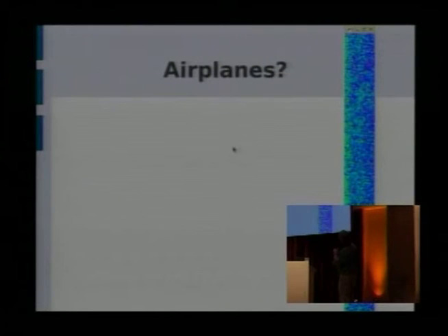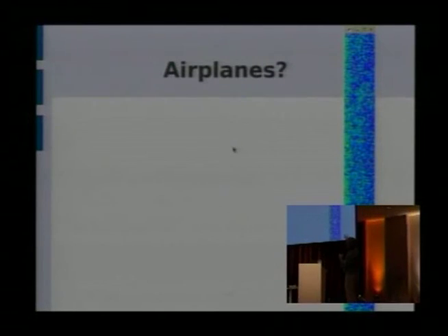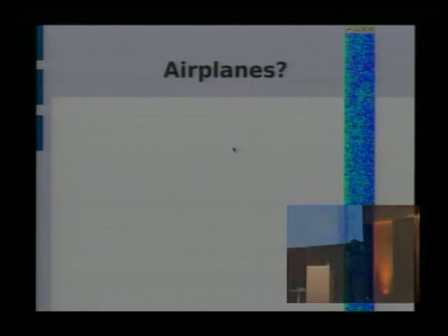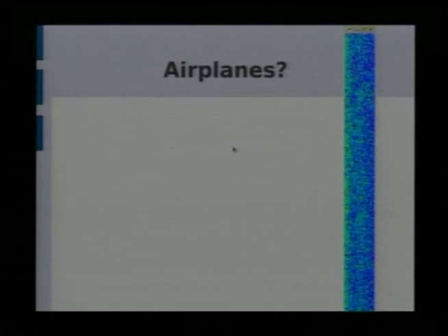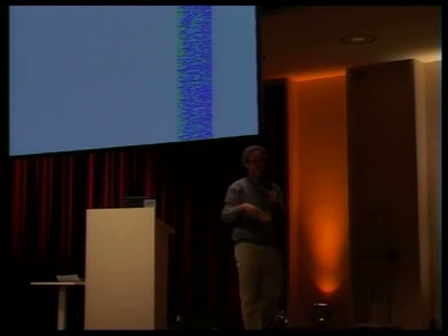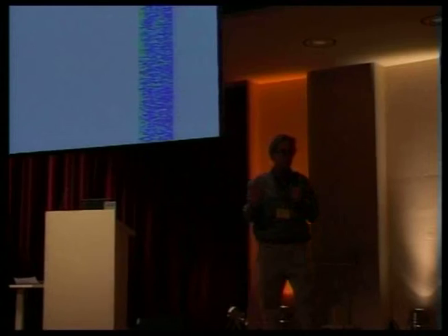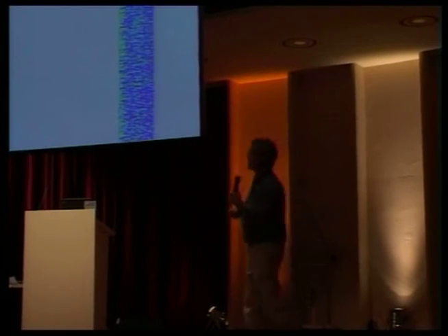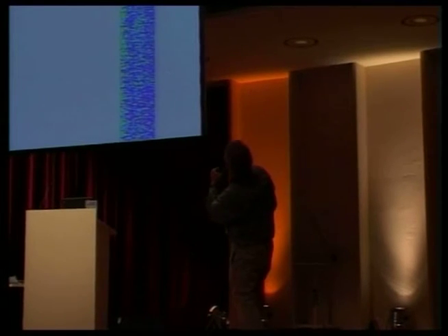The y-axis is Doppler. This has lots of bins in it. The way this was plotted up is there's 256 possible frequency offsets that it could be at. And this is about 30 pixels wide here, 30 bins wide this way, which is about out to 30 kilometers. The airplanes were closer than 30 kilometers, so I figured they ought to be in there. Well, I don't know about you, but I don't see any airplanes in there.